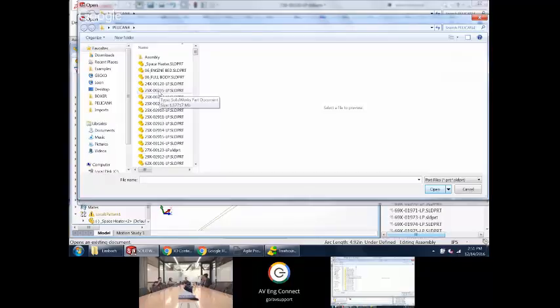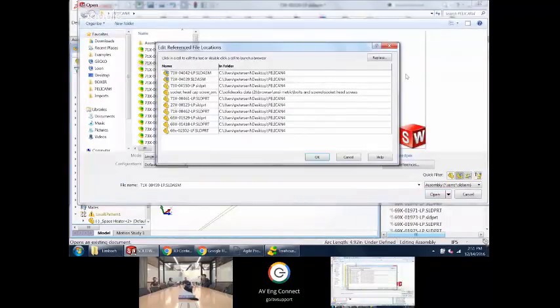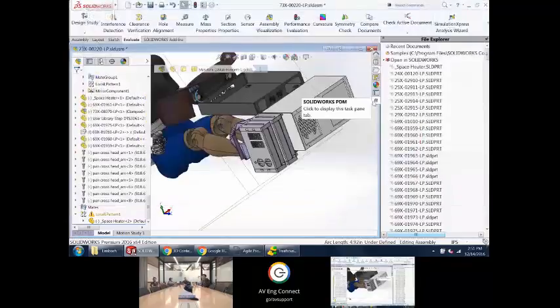Could you fix this one? like it does when you do it live, if you do it this way, all the mates just blow up and you have to go and fix them manually. So that's why I typically like to do it from an open assembly, so that rather than me pulling the rug out from underneath a mate, I can go through there and say, okay, this face goes here, this face goes there, and have a lot more confidence in the thing being put together correctly.